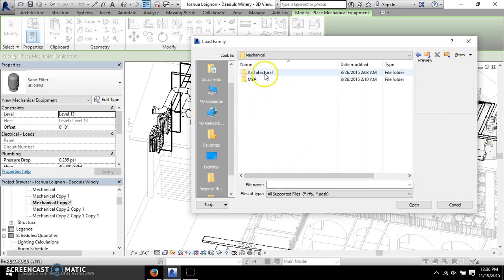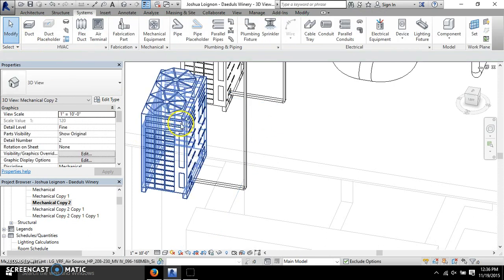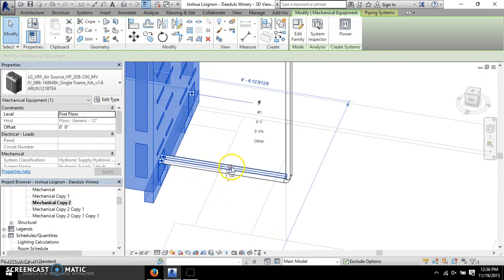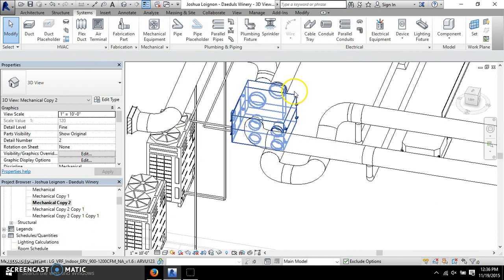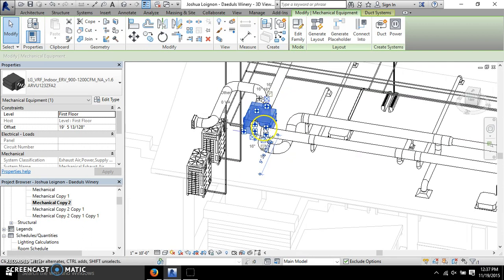Again, if you hit architectural, you won't get the branch offs for it. If I click on this mechanical piece of equipment, you see how I get the refrigerant line pipe and things that I can draw pipes out of. For this AHU, I get the refrigerant lines, and then I get the supply lines and the return lines for all the ductwork.